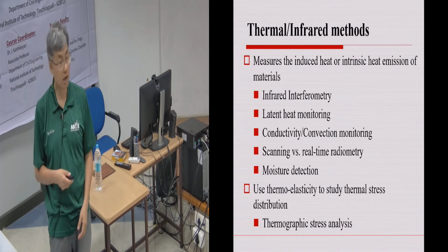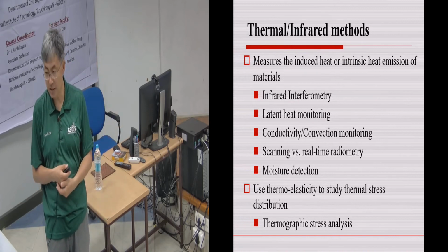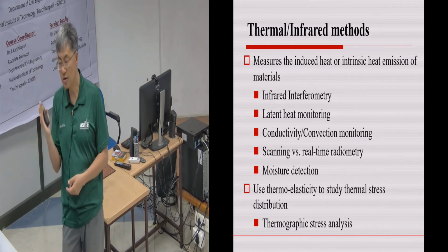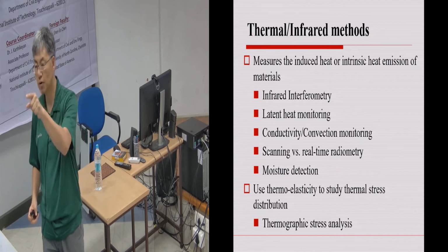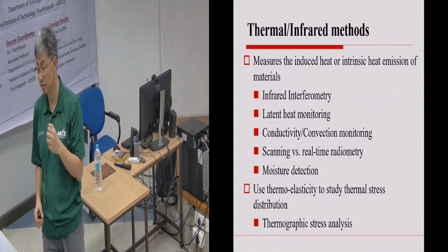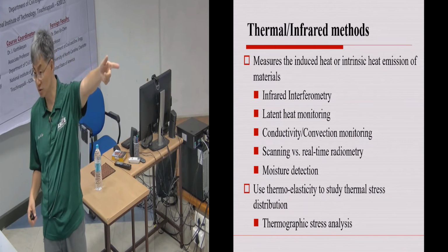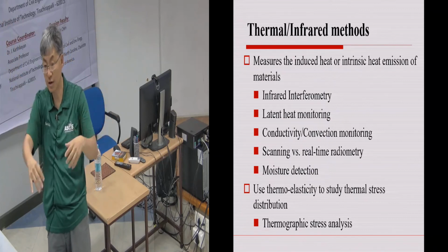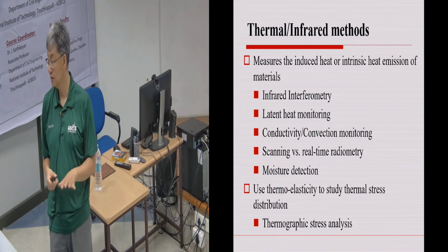Okay, and then infrared, as I mentioned. So the infrared method depends on the temperature release. Okay, so it's a very important thing to understand. Infrared is not measuring the temperature property of that material. It's the temperature release of that material that you're measuring. Okay, so when we apply infrared on a structure outdoors, usually we do it at night. Okay, it's when the temperature is cool and the sunlight has already hit off the concrete, and when the heat is coming out, then you are seeing what's underneath the structure.